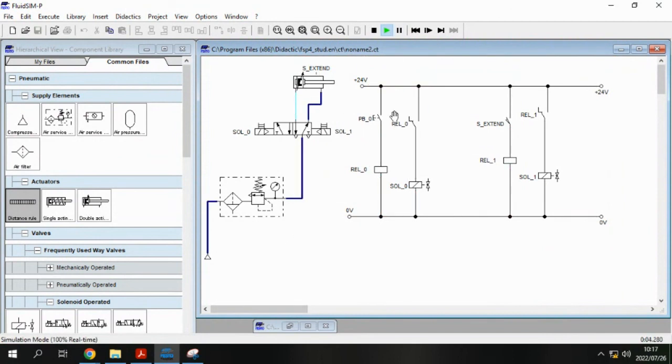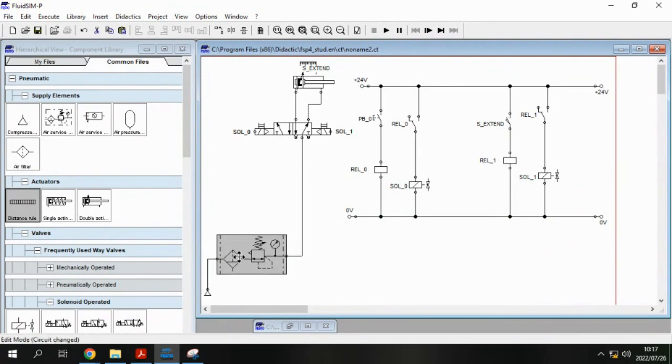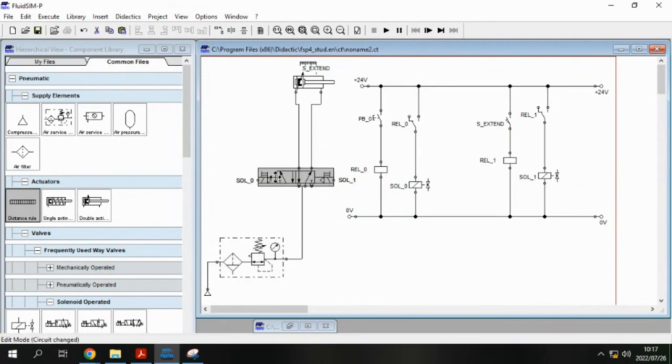But it's happening very fast. It's coming back very fast. So to slow up the process, we're going to put what? One-way control valve. Let's put it there. So in order to put it nicely, break down your compressor so that you can have enough space.